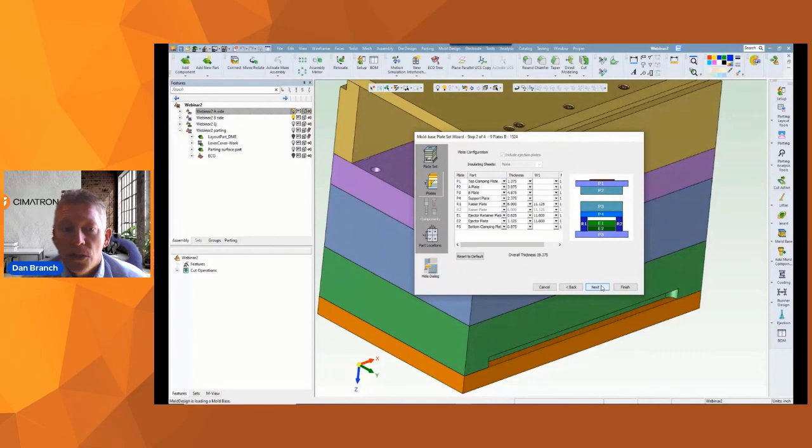About the only thing I did was choose to delete the standard sprue bushing. The center holes in this mold are going to be offset anyway. Plus, we can look at adding the first of those new DME parts, a sprue bushing that has cooling channels in it.